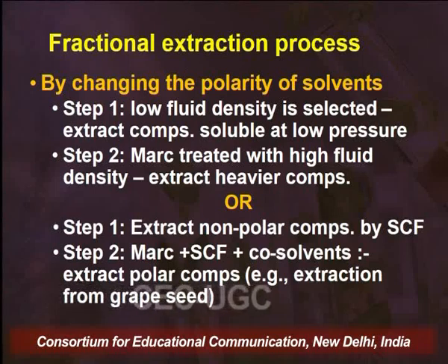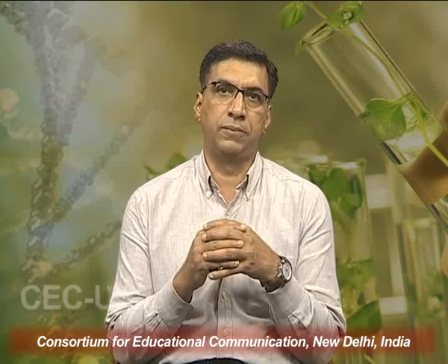Now, supercritical fluid extraction can also be carried out in a fractional manner, which we call the fractional extraction process. Many times we require extraction of different types of constituents based on their polarity. So, in order to extract different constituents on the basis of their polarity, we use the fractional extraction process.